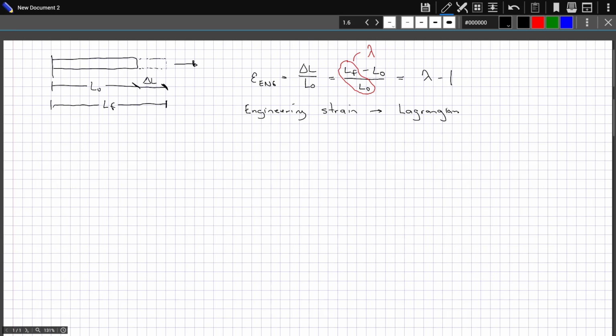And of course, in a geomechanics setting, everything in the earth is deformed due to tectonic stresses. So reference frame is a better word, or the Lagrangian frame. But sometimes again you'll hear the word undeformed. Okay, so because we reference the undeformed L0, the original length or the reference length, that's why this is often called a Lagrangian strain.